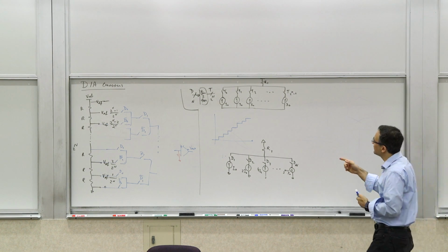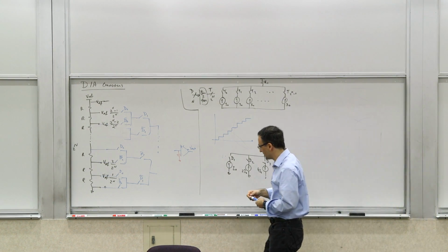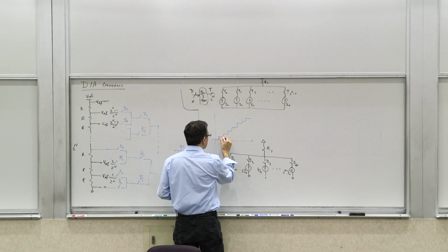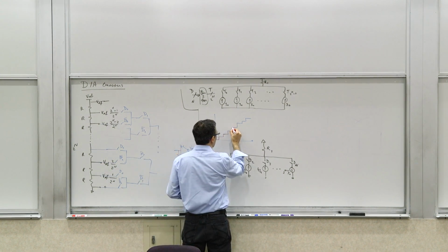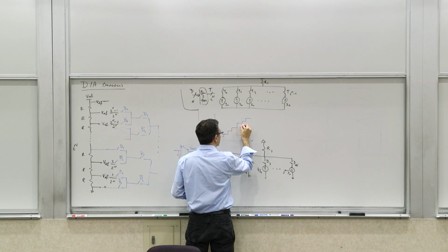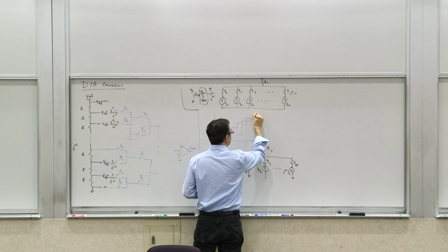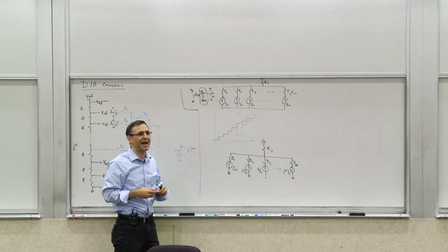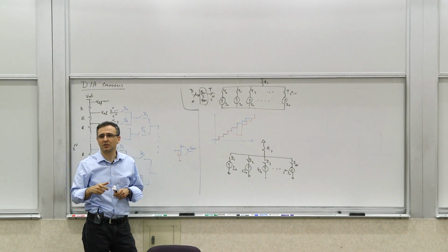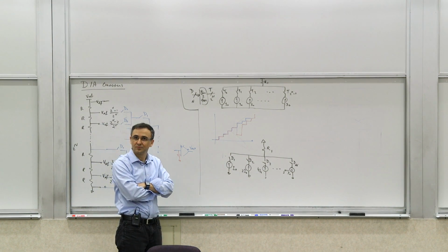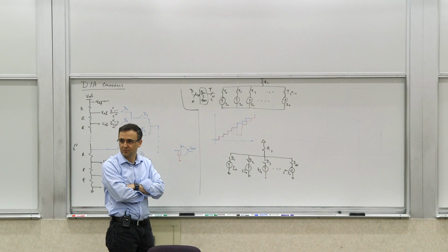One thing that's very common in this kind of D2A is that you may see something like this at some point in the response. Why would that happen? It can become non-monotonic. Yes? Because a larger current source is kicking in, and the error in that one outweighs the rest. Exactly.